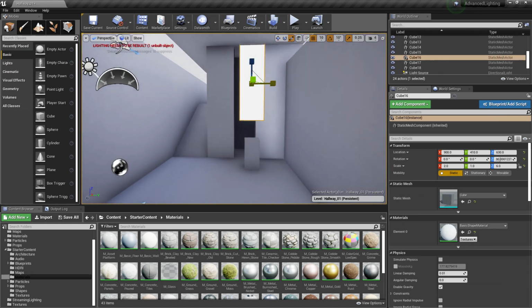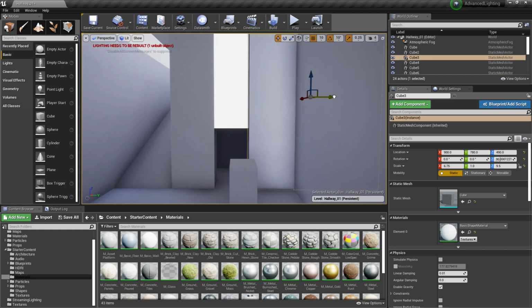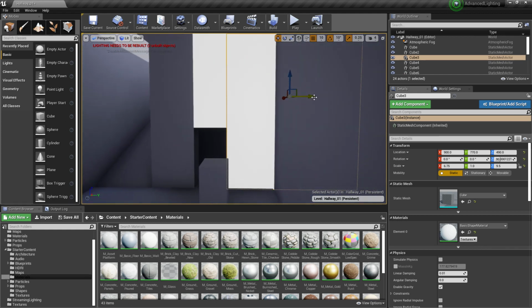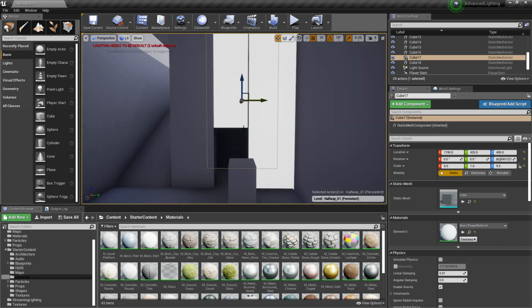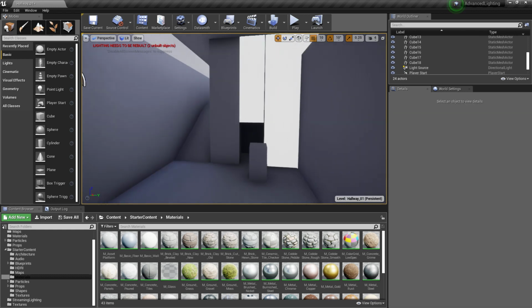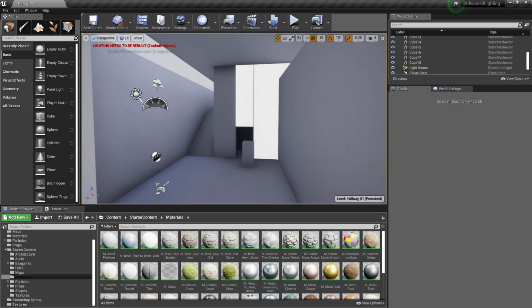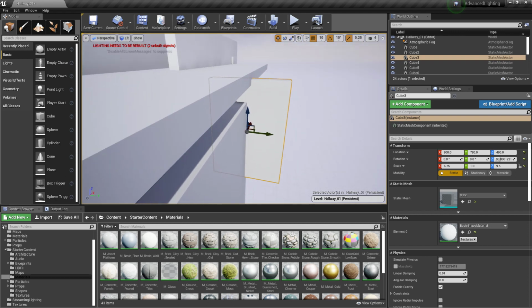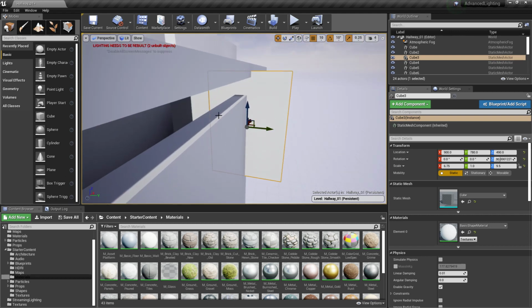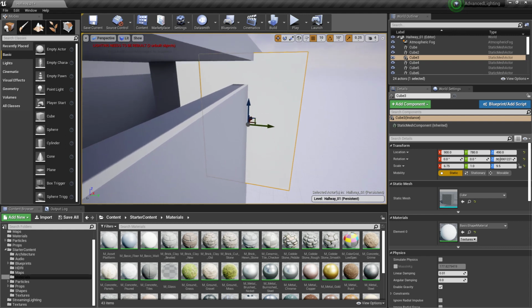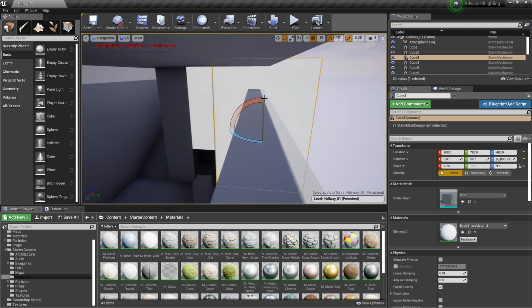First and foremost, let's scale this one down so that they're not overlapping, just for now. What you would really want to do is come in here and actually set them to be grid snapped. Again, when we actually do the real one, we can change that. I'm also going to scale this mesh down. What's happening is it was a lot brighter, because light was hitting the outside edge of this mesh and literally sucking light across because the resolution was too low. So the whole thing kind of brightened up.